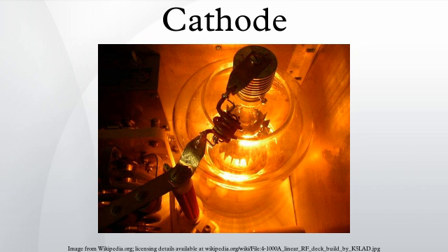When p and n doped layers are created adjacent to each other, diffusion ensures that electrons flow from high to low density areas, that is, from the n to the p side. They leave behind the fixed positively charged dopants near the junction. Similarly, holes diffuse from p to n, leaving behind fixed negative ionized dopants near the junction. These layers of fixed positive and negative charges, collectively known as the depletion layer because they are depleted of free electrons and holes. The depletion layer at the junction is at the origin of the diode's rectifying properties.